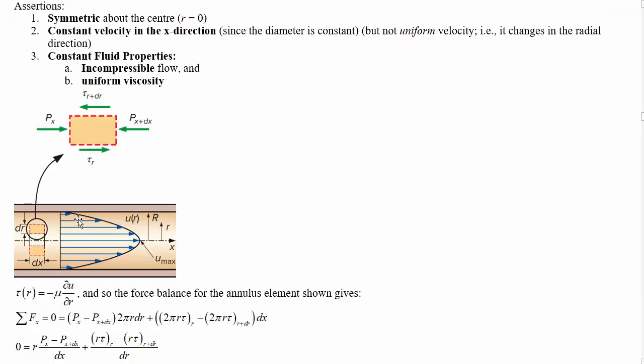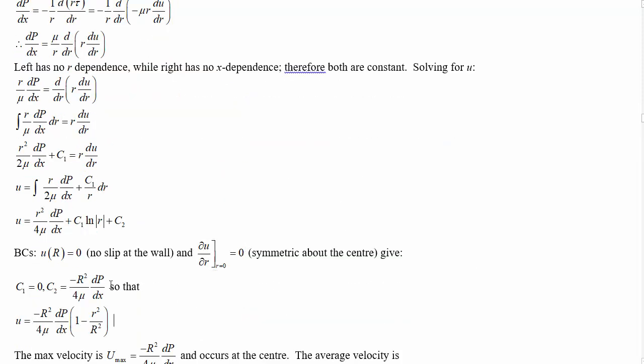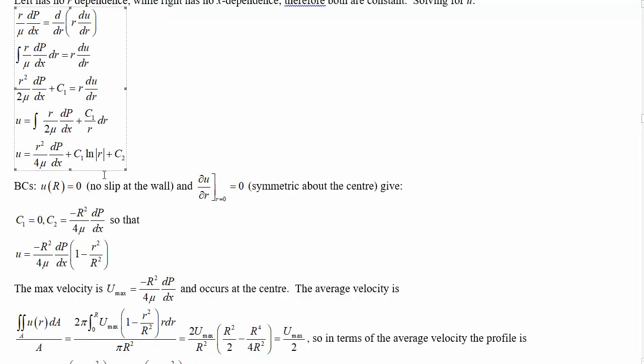So whether it's maybe a parabola or maybe a cubic function or some kind of a square root type thing, we haven't really made any assertions about that, but whatever we would get for some reasonable velocity profile, there's nothing special about the bottom versus top of the pipe, so we have a symmetric velocity profile about the center. Okay, this means when we apply the boundary conditions, we can solve for those two constants in this particular case and end up with this as our velocity profile.